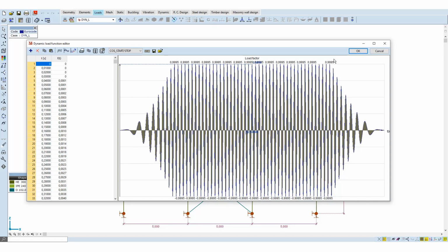Even if the operational excitation frequency of the machine is far away from the natural frequency of the structure, often the structure is undertuned, meaning that during acceleration or deceleration, the frequency of the machine will catch the natural frequency of the structure for a short period of time. This leads to an instant resonance and to an impulse force causing high amplitude vibrations. This vibration, however, is a free vibration and will decrease over time through structural damping.